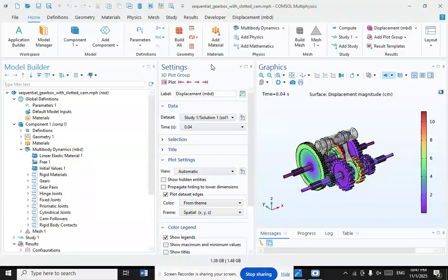This is a fundamental difference compared with the typical hydraulic automatic transmission, which uses an epicyclic planetary design and a hydraulic torque converter. An automatic transmission that allows the driver to control the gear selection, such as shift paddles or positive and negative positions on the gear selector, is called a manumatic transmission and is not considered a manual transmission.